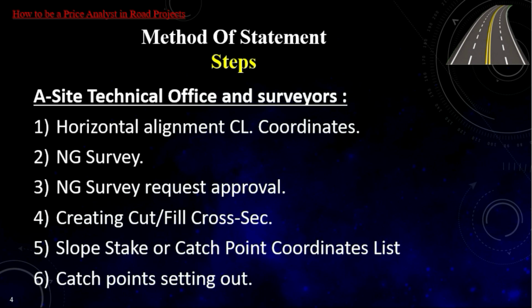1. Horizontal alignment centerline coordinates. The Site Technical Office engineer prepares a list of the coordinates of the road centerline agreed upon by the supervising engineer, and delivers it to the surveyors.